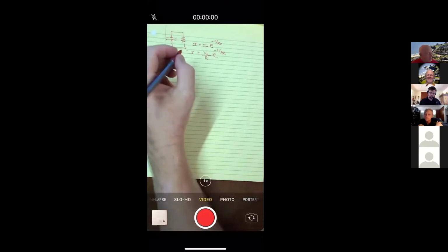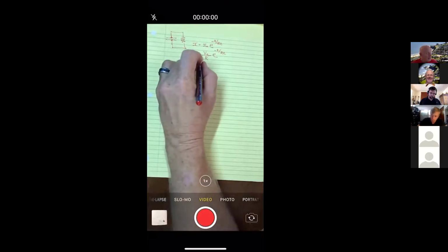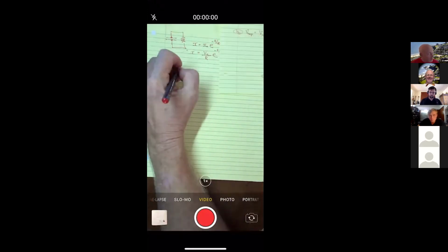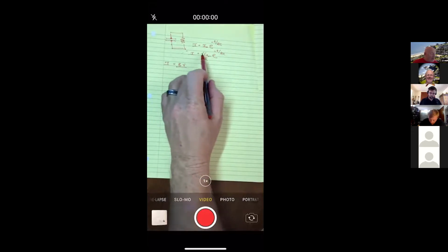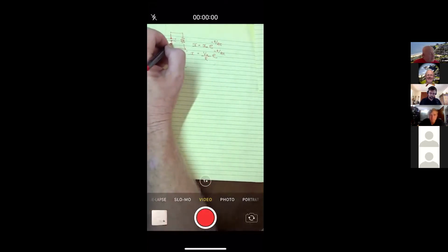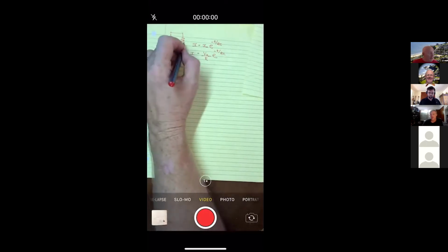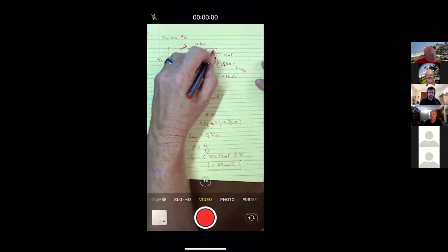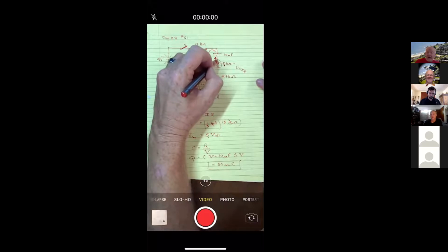And so to get the answer here, we have to ask what voltage it starts at. Well, that was back here in part B, 5 volts. I'm going to put 5 volts. And then this is the resistance that it goes through to discharge. Now, I must say, when we derived this, we only had one resistor, but this problem looks like when it discharges, it has to go through this 15 and then also through the 5 that are in series.